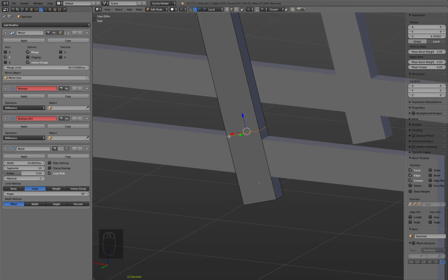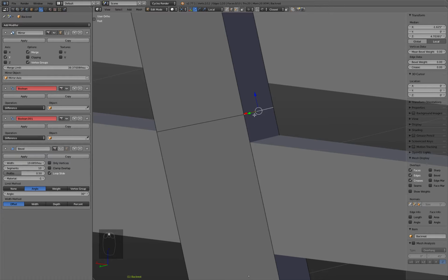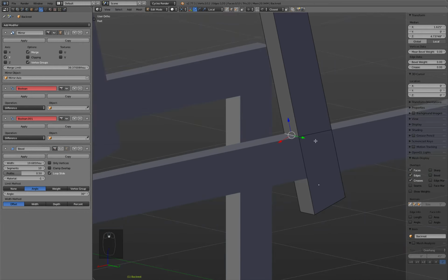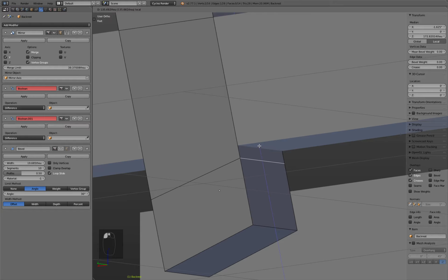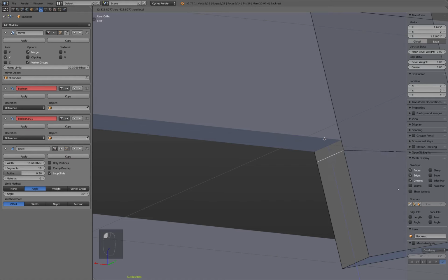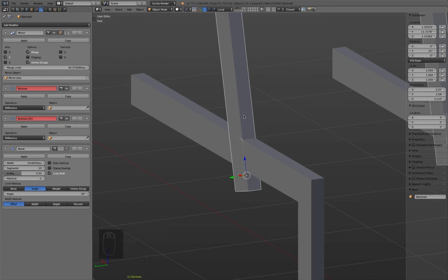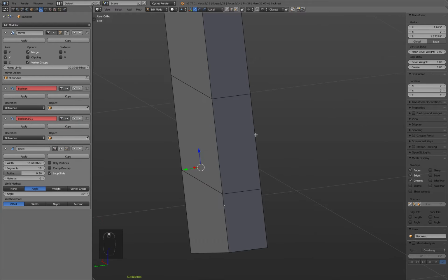And you see this loop cut goes along the rotation of the object. That's not very good, but we can select, for example, this edge and then move it down and then try to match this up. Okay, good. Maybe one more down here, and then you see again I use local space, pretty awesome, to that transformation I move it to there. Okay, good, also works. Let's hide everything else because now we have to decide where do we slice something out.